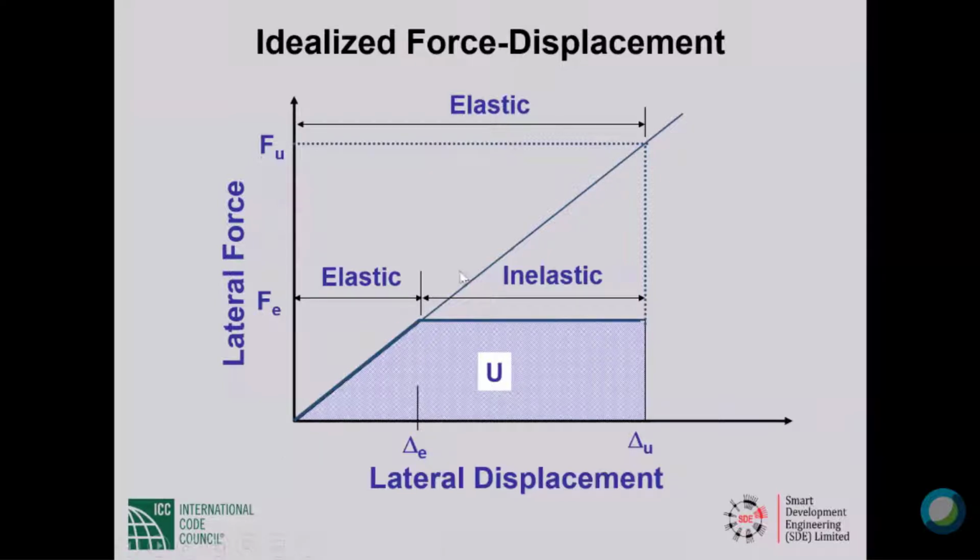Elastic response does not have to mean force proportional to displacement as shown. Elastic really means no residual displacement. The earthquake passes, we get our structure back intact, and importantly, located where it was before the earthquake, not some distance away from where it was.